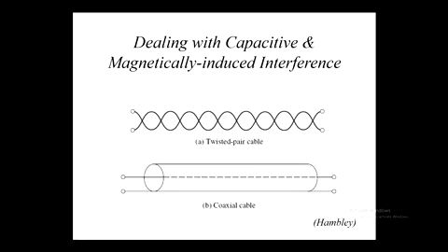The ways that we do it, of course, is the coaxial cable, the shield around the outside of the connector, or a twisted pair. The signal lines are twisted around each other. That means that both the wires experience the same amount of interference induced in them. So if we then take our signal and use a differential amplifier on it, as you well know, we cancel out the interference and preferentially pass the signal as a differential signal.